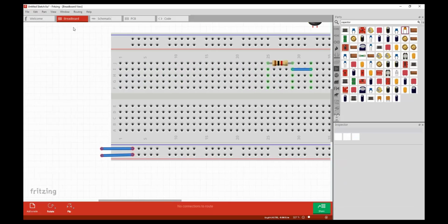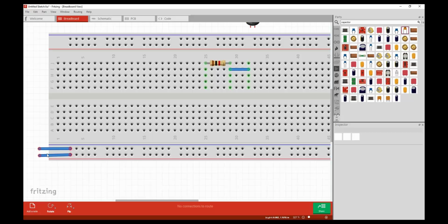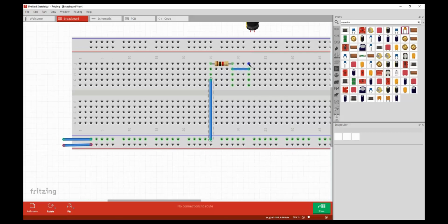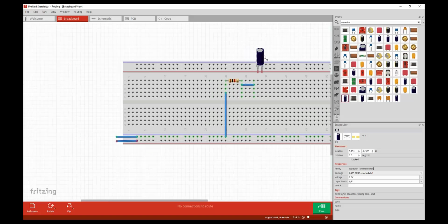You do not have a function generator here, but normally when you would be doing this in lab, you would take this to the function generator input. So let me define the top one as positive and let the bottom one be negative. That means if I connect a resistor between this and this, the electrolytic capacitor connected here, this terminal should be the positive one, because that's the one which will be connected to the positive cycle. Okay, but here since it is negative, I need to flip this. So I was not able to change the values of that capacitor.